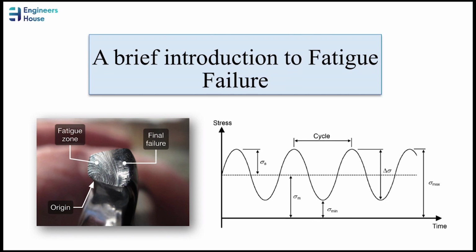It is frequently seen that machine members are found to have failed under the action of repeated or fluctuating stresses, even though they haven't reached their ultimate strengths or even their yield strengths. This type of failure that occurs due to these repetitive cycles over a long time is called fatigue failure. In today's video, we'll focus on completely reversed cycles.